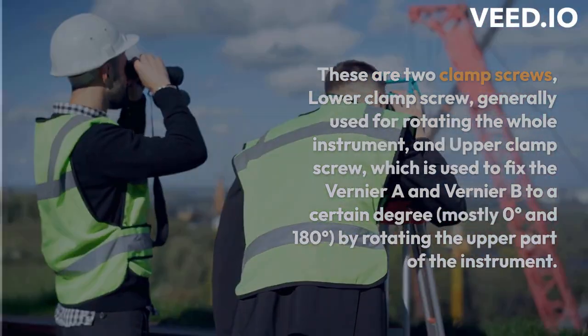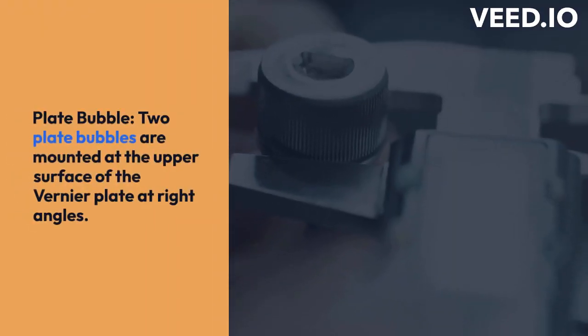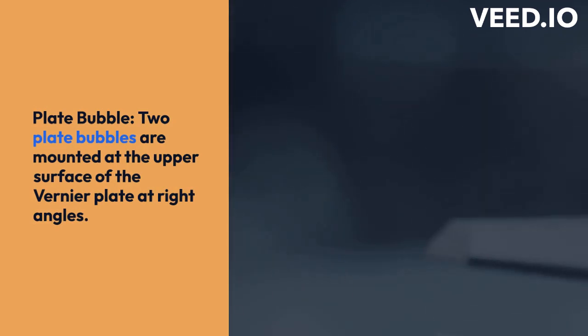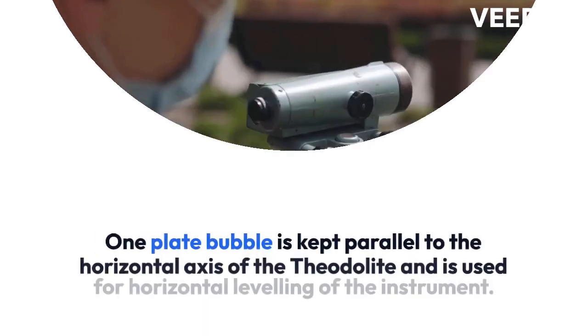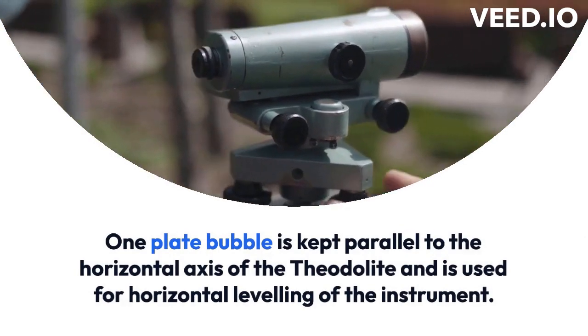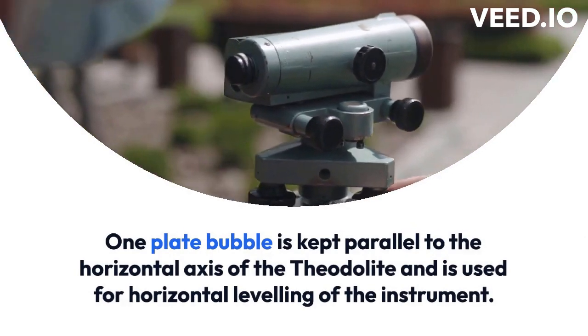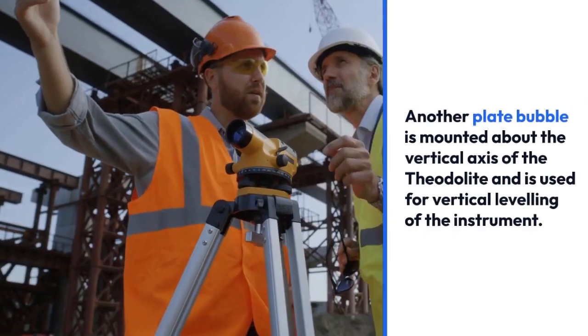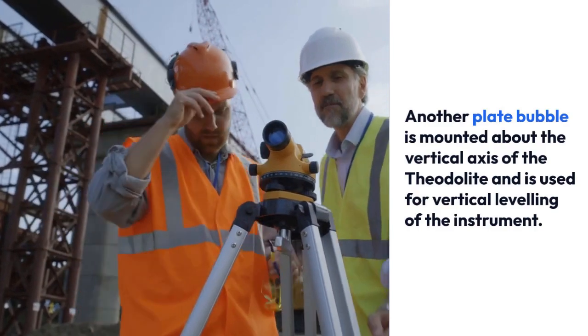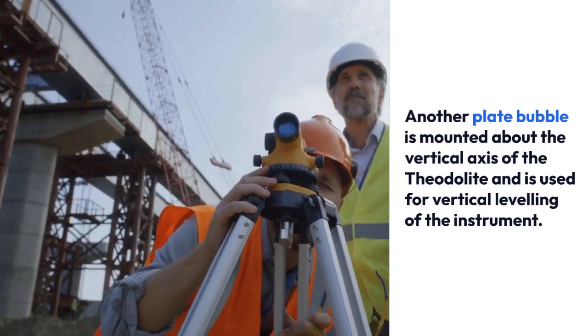Plate bubble. 2 plate bubbles are mounted at the upper surface of the vernier plate at right angles. One plate bubble is kept parallel to the horizontal axis of the theodolite and is used for horizontal leveling of the instrument. Another plate bubble is mounted about the vertical axis of the theodolite and is used for vertical leveling of the instrument.